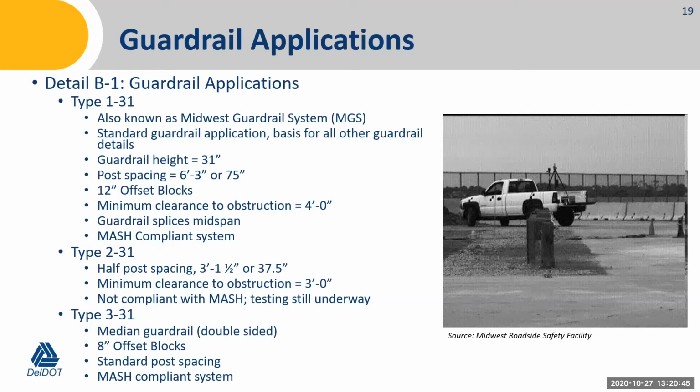MASH testing is still underway with this system. They're having some issues with transitioning from the standard post spacing to the half post spacing. So for now, until we have a suitable alternative that's MASH compliant, we'll be utilizing the existing 231 detail.